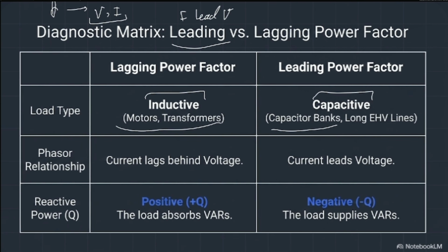So for the amplitude, we are talking about, for instance, at this point, the voltage itself. By the way, most of the time, voltage is considered as a reference. So whenever we are talking about the voltage, it means the magnitude of voltage, and after that the phase of zero itself. When we are talking about the leading, it means that current reaches its maximum faster than the voltage itself. So at this point, I do have my current like this.